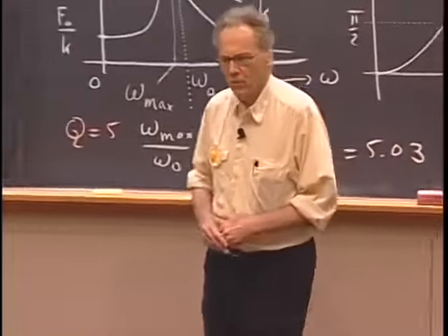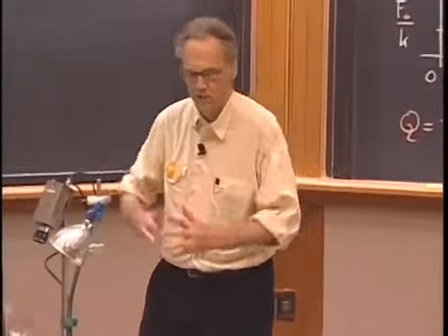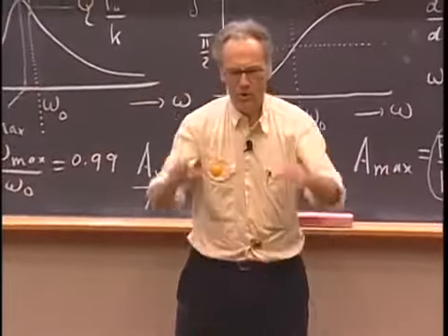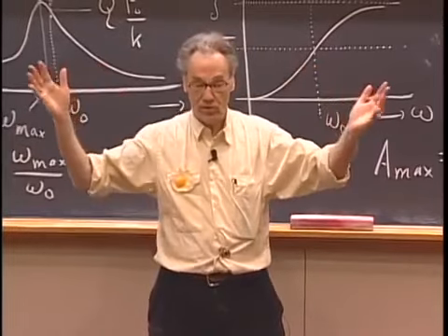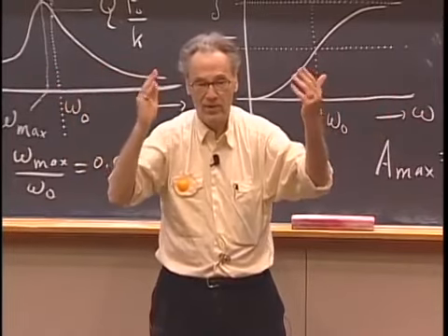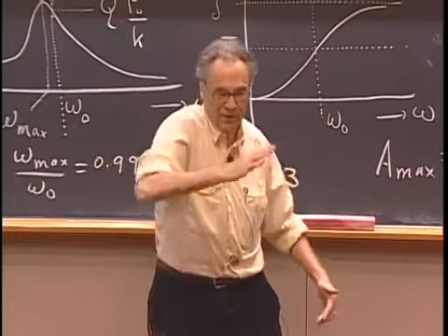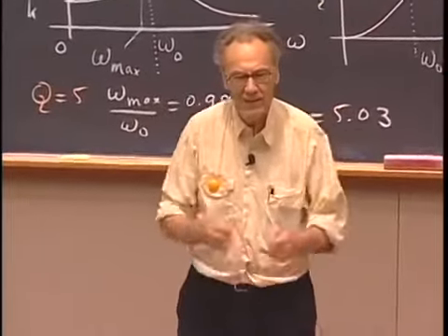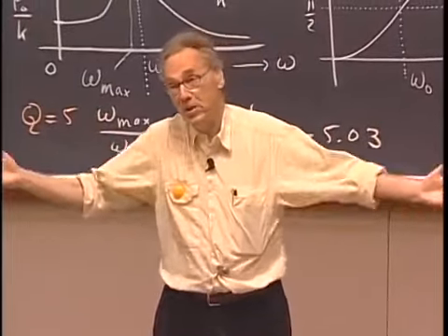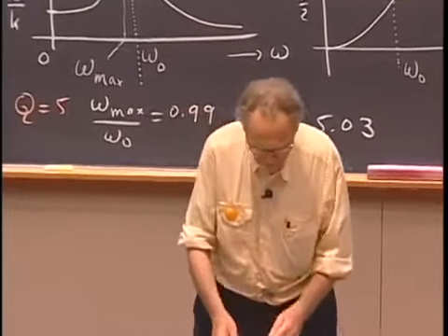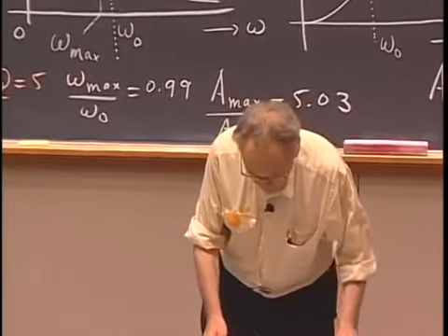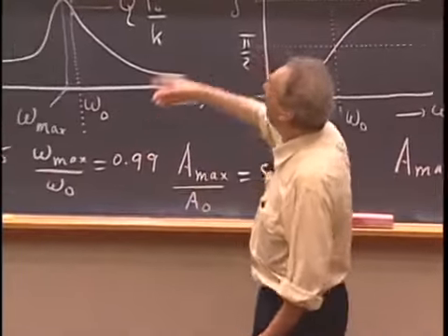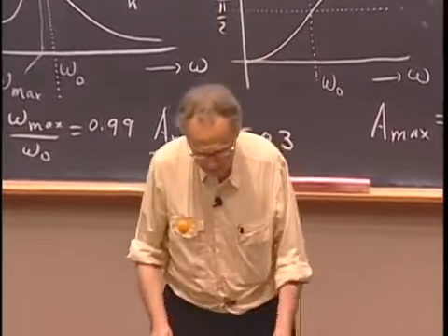You've seen footage lately of the storms, 3 storms in a row. And you must remember sometimes that you saw a traffic sign. You see a pole, and then a traffic sign. And even though there's some kind of a crazy wind going, the traffic sign goes like this. All resonance frequencies. It can even break. Even though the wind appears to be relatively steady, the wind then generates, in a way, a whole spectrum of frequencies, and this traffic sign picks out the one that it likes the most, and then it goes nuts at a frequency that is a resonance frequency.